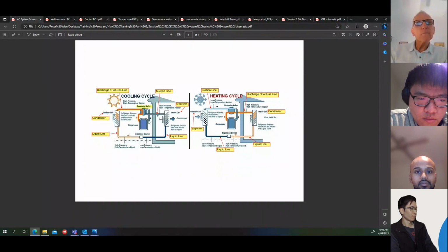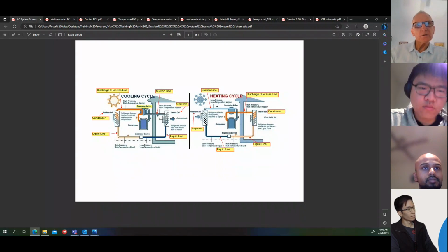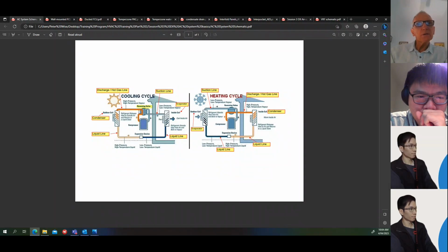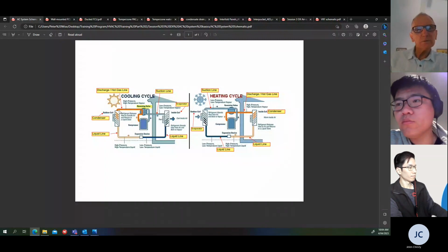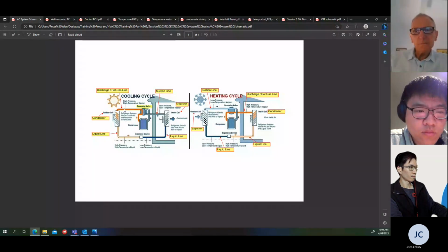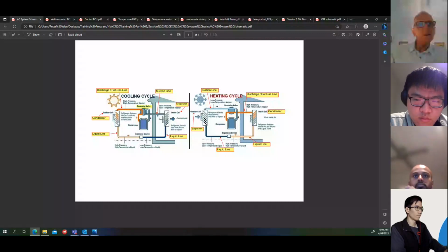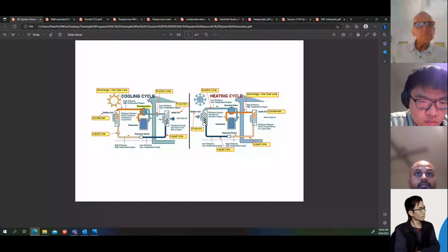That's drawn into the compressor through the reversing valve, and it's compressed into a high pressure, high temperature gas or vapour. And that line then carries it through to the condenser. And the line is called a discharge line or a hot gas line. Okay, so that's a hot pipe. It goes to the condenser, and the condenser then rejects the heat to the outside with the help of the condenser fan. Or an outdoor coil, condenser is a common terminology. And that turns the refrigerant into a liquid.